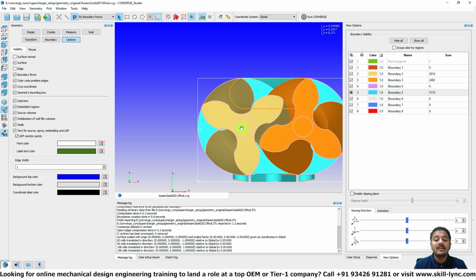Typically, when you get data from a company, these type of issues do not occur. We are seeing these type of errors because, like I said, the geometry is made up. What is the possible solution here? Well, what we can actually do is, we can scale down the geometry so that the lobe is not intersecting with the outer casing anymore.